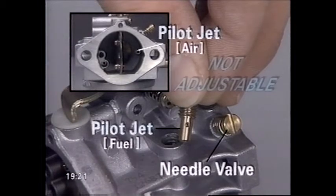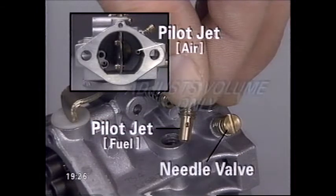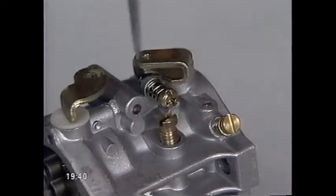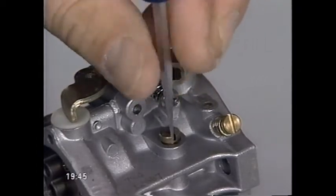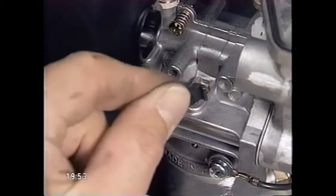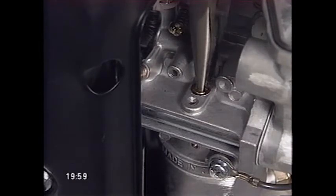As with the pulse, the pilot air and pilot fuel jets are not adjustable, and the pilot needle valve is used to adjust only the volume of the fuel-air mixture entering the carburetor, not the ratio of fuel to air. The pilot jet must not be installed too tightly, only finger tight. Over-tightening can distort the intended position and will affect the fuel and air mixture. Some float carburetors come equipped with a screw and clip to lock the position of the pilot jet in place after adjustment. This is done to properly locate the pilot jet with respect to the air passage.